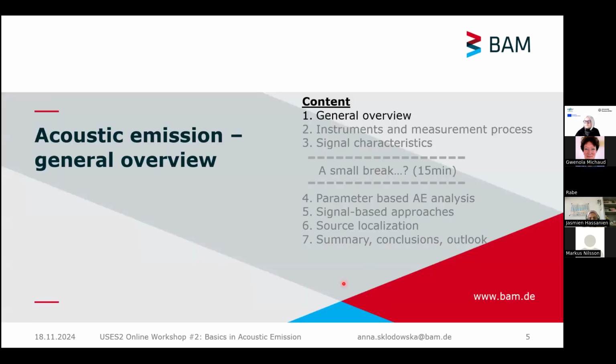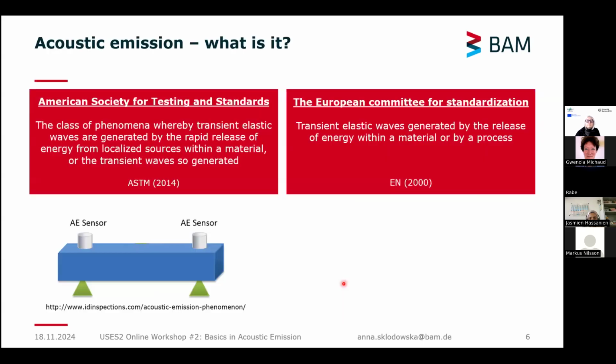Okay, so coming to the first part, I will start with the general overview. When we say acoustic emission, what do we actually think about? There are some very defined definitions given by two standards offices. The first one comes from the American Society for Testing and Materials, and acoustic emission is defined as a class of phenomena whereby transient elastic waves are generated by the rapid release of energy from localized sources within the material, or the transient waves so generated.